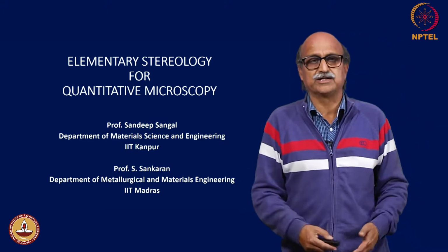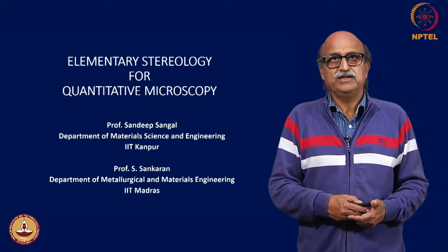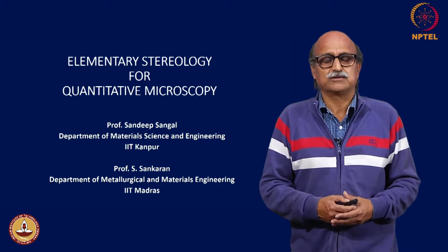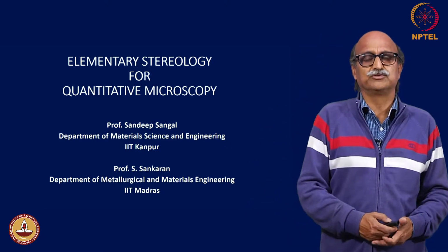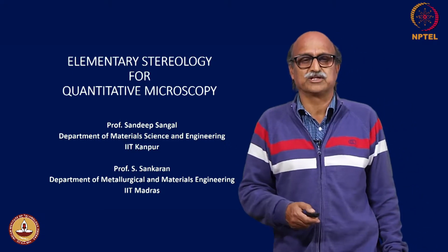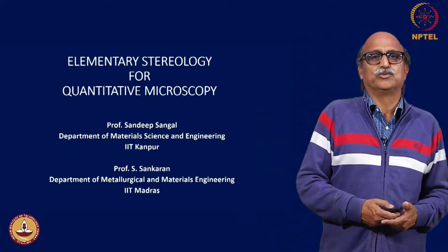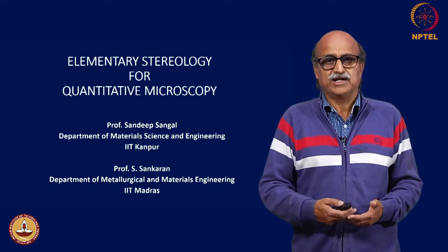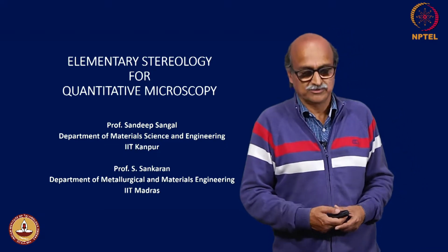The underlying technique for quantitative microscopy is stereology, and here we will look at the elementary stereological tools. Stereology is strongly based on mathematics and probability and statistics, because the microstructures that you are trying to quantify are stochastic in nature, and hence they have to be dealt with through statistical methods.